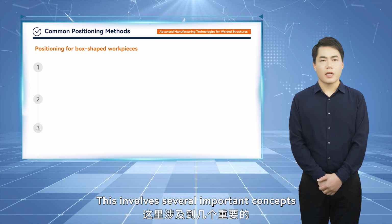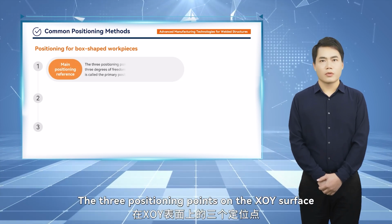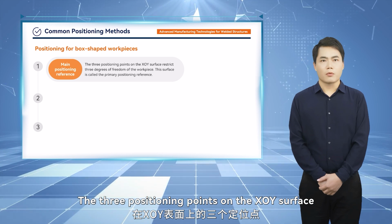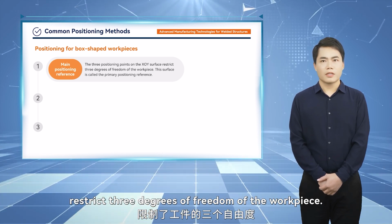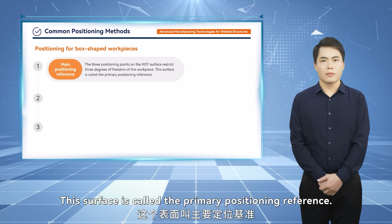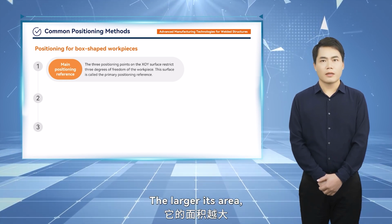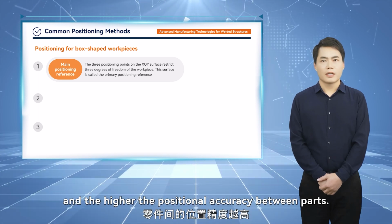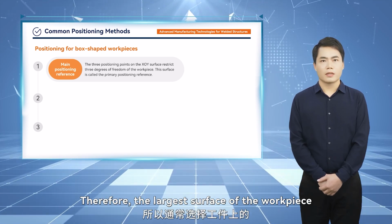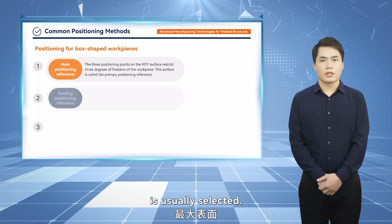This involves several important concepts of positioning references. The 3 positioning points on the XOY surface restrict 3 degrees of freedom of the workpiece. This surface is called the primary positioning reference. The larger its area, the more stable the positioning, and the higher the positional accuracy between parts. Therefore, the largest surface of the workpiece is usually selected.